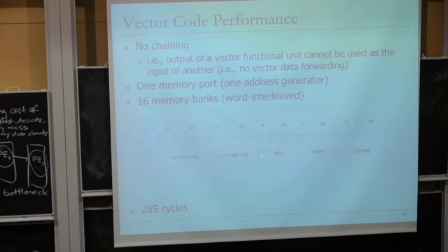Now you have both vectors in registers vector 0 and vector 1. Now you can do the add. The first add on the first element completes after the 4th cycle, and remember we have a pipelined adder, so the sums of the remaining elements each finish in consecutive cycles, so 49 cycles. And you can do the same thing for shift and store. So if you do the calculation of this, it takes 285 cycles. And we haven't really optimized anything yet.